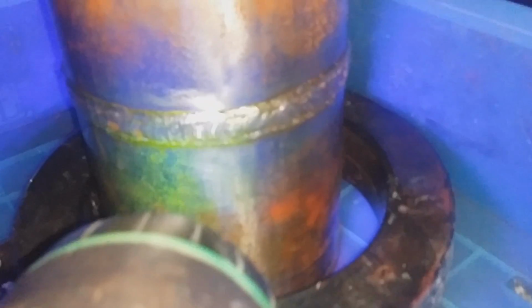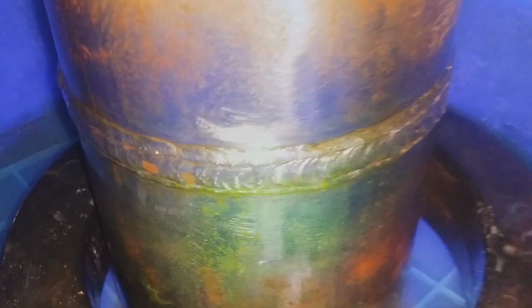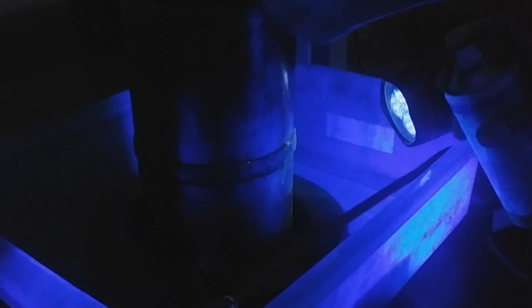This is referred to as the continuous method and will reveal defects at right angles to the coil axis. While using the wet method, allow the coil to remain energized for approximately 2 seconds after applying the wet medium. Remove the part for inspection. The longitudinal magnetization technique is more effective with pipes because the coil around the material will be better than for other shapes of materials.